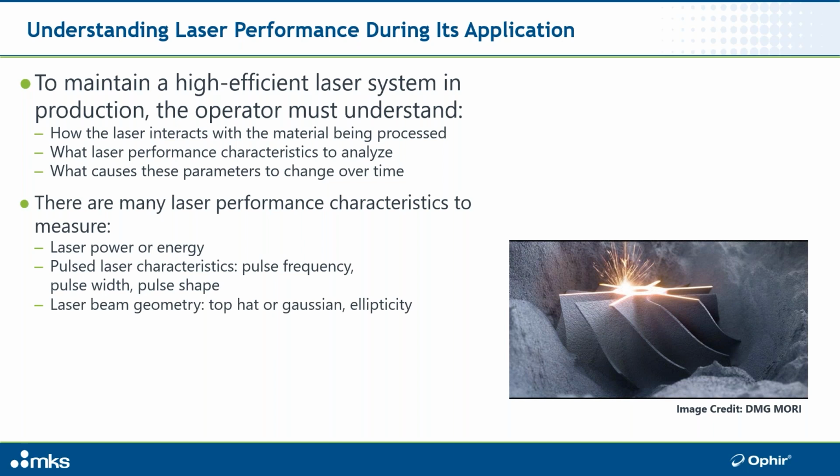We go into the laser beam profiling part of the measurement. So is it a top hat? Is it a Gaussian profile like it's designed to be? Understanding the shape of the beam, the ellipticity, the roundness of the beam. And then the focus spot position. If you are presenting the focus spot to your process, is it where it's supposed to be, number one? And after the laser beam is on, if there is a thermal effect on the laser system, like we saw in that case study, is that focus drifting off of where it's supposed to be? So understanding where the focus spot is and if that location is changing over time is very important.